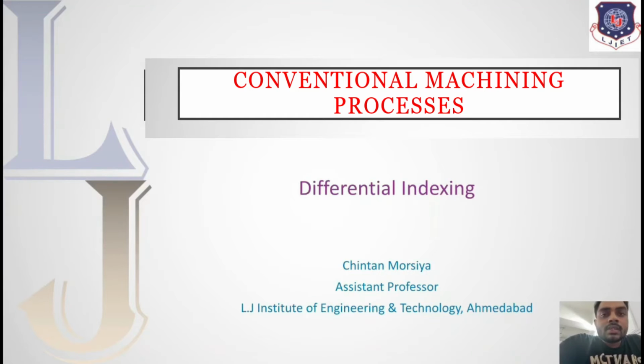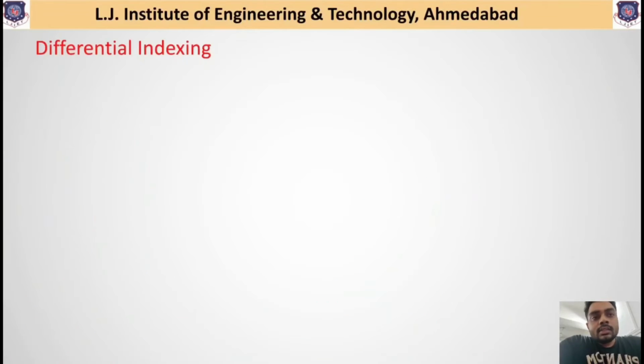Hello students, today in this lecture we will discuss differential indexing. As we have discussed in our previous lecture, we will also understand what is the difference of this differential indexing method compared to that compound indexing method. So to understand this differential indexing method, let us have a look at a simple arrangement that is available in the universal dividing head. Because compared to the universal dividing head available in maybe compound indexing method or simple or plain indexing method, there are certain changes.